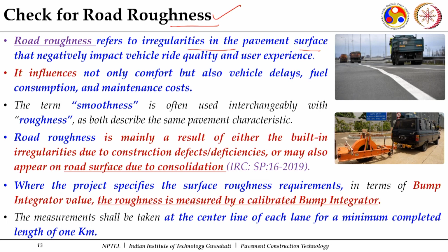You might have observed on some of the older roads that it gives a bumpy ride. Specifically, there is some wavy sort of structure. So, when you drive at higher speeds, you experience it, and even when you drive at a slower speed, if those are closely spaced, you can experience those bumps or the wavy structure. So, it influences not only comfort, but also vehicle delays, because you can't drive at the design speed, fuel consumption is high and maintenance cost increases. So, it is always preferred that you get a good riding quality.